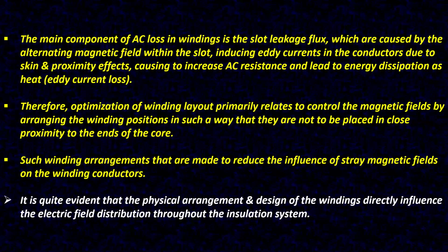Therefore, optimization of winding layout primarily relates to controlling the magnetic fields by arranging the winding positions in such a way that they are not placed in close proximity to the ends of the core.